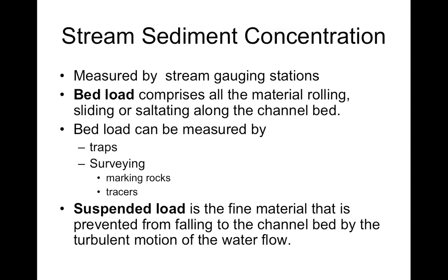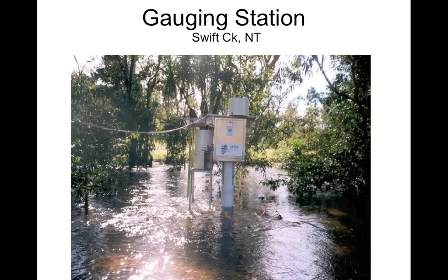You can look at things like slope and plot length and play with that and come up with a good design. Now you can also measure things like the stream sediment concentration, both as bed load or suspended load in rivers. And here is, it's not very informative, but trust me, there's a logger which is sampling water quality. There's a water quality sampler here. But within this device here, you can sample the suspended load and estimate how much erosion is happening across your entire catchment.